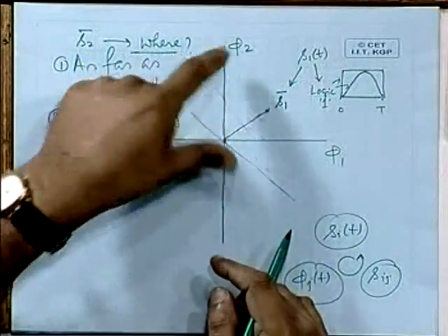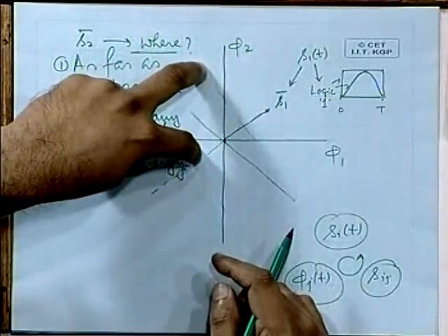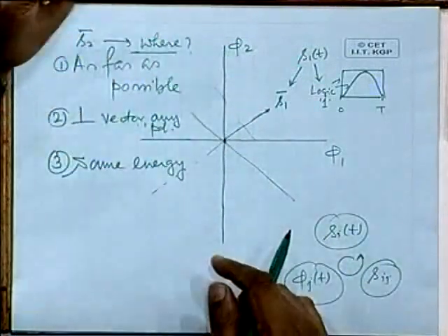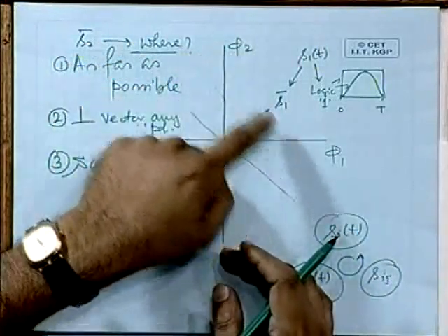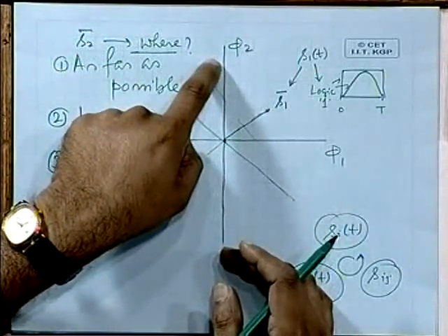Still, it is good. I'm not telling you to define BPSK in terms of two quadrature carriers, because the same description of signal space will be used very extensively for finding out the operation of the receiver, where, because of problems of carrier signal recovery, you may again find a second dimension is good. So this is an example deliberately taken, where on the one hand it was not necessary to describe two points using two basis functions, but because BPSK is a very important phase modulation scheme, for the general receiver description it may be a good idea to talk about two orthogonal carriers.